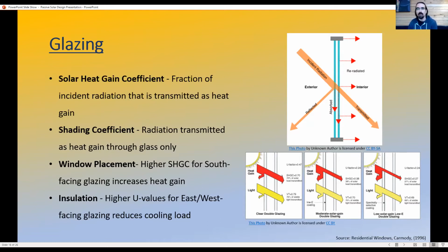Something that's important to know with solar heat gain coefficient is that it rates the entire assembly. So it's actually testing how much energy is being transferred through the entire window assembly, the casing, the frame, and taking that into account for how much energy is absorbed. Something you may see more in a commercial setting is shading coefficient. And the shading coefficient is rating the glass only. It's not looking at the transfer of energy through the window assembly. This might be important in areas where you might be fabricating the window yourself. It might be a type of window that's not available pre-manufactured. You might just be building a new window out of a piece of glass, but you want to be able to know exactly how much is transferring through that piece of glass. And like I mentioned, you may want to use different levels of heat gain coefficient in different areas of the house. Some parts of the home you may want to be getting a lot more energy through the window.